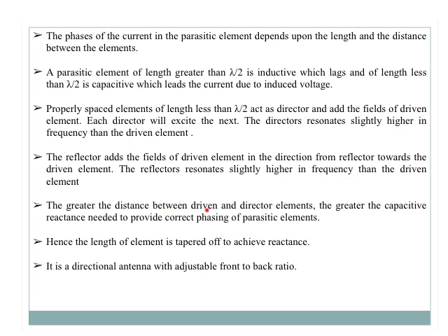The greater the distance between driven and director elements, the greater the capacitive reactance needed to provide correct phasing of parasitic elements, as the length of the element is tapered off to achieve the reactance. And we can say that this Yagi-Uda antenna is a directional antenna with adjustable front to back ratio. This is very important with respect to the Yagi-Uda antenna.